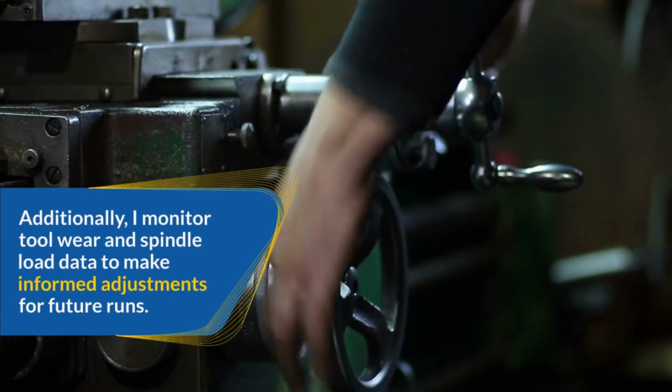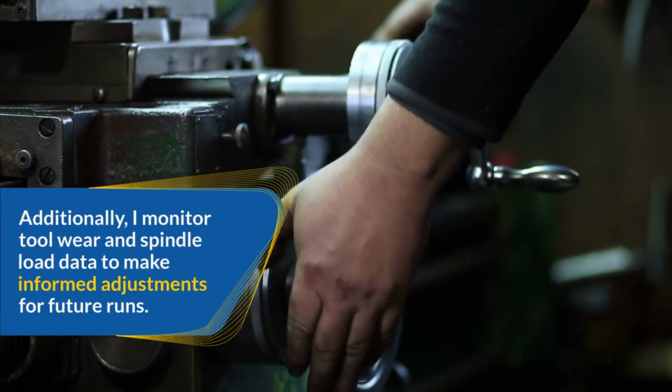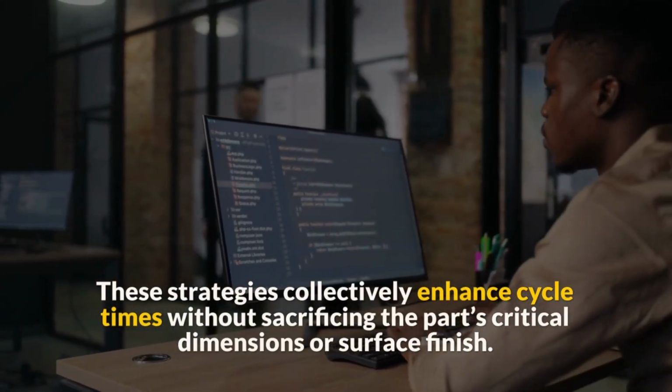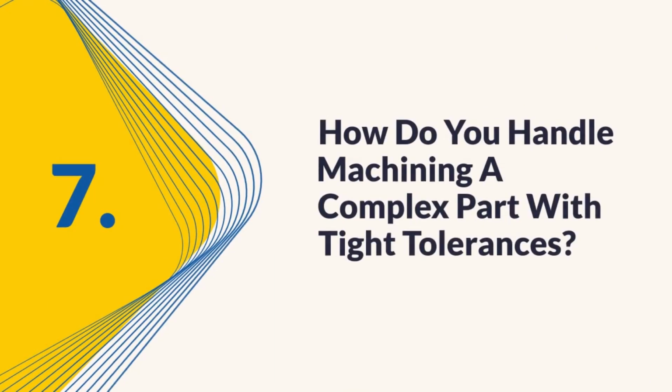Additionally, I monitor tool wear and spindle load data to make informed adjustments for future runs. These strategies collectively enhance cycle times without sacrificing the part's critical dimensions or surface finish. 7. How do you handle machining a complex part with tight tolerances?